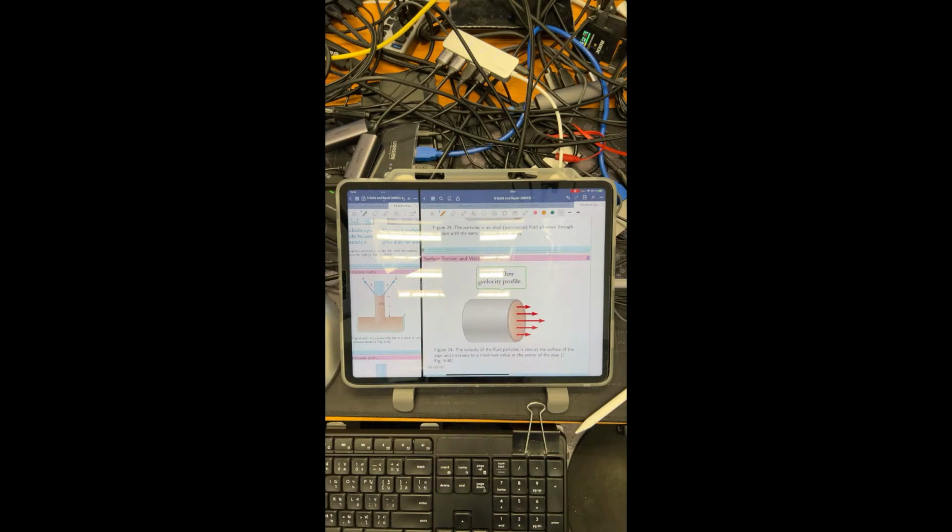Now let's consider the realistic viscous flow velocity profile. In this case, the fluid is in reality. When the fluid flows, there is friction between the liquid and the metal inside. It's called internal friction. Among several layers of fluid there is also friction, but it's not so strong as the friction between that fluid and the internal wall of the pipe. So there is high friction here, low friction here. With the low friction, the fluid can move easily. Easy movement means high speed or high velocity of the fluid flow here.